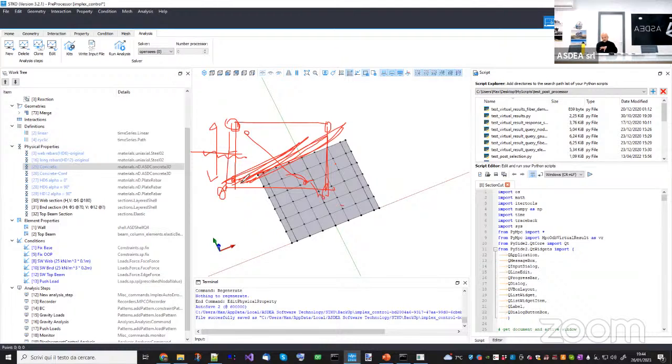And so our anisotropic internal variable is trying to mimic this thing here. So the concept is that if I'm damaging in this direction, because I was shearing like this, I want, when I shear in the other direction, to have the same strength, because now this opening will close, and now we'll need to open a brand new crack to show softening on the other side. Okay, so there are two different aspects. I don't know if it is clear.